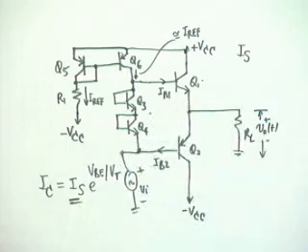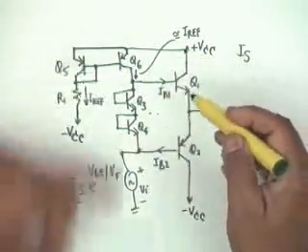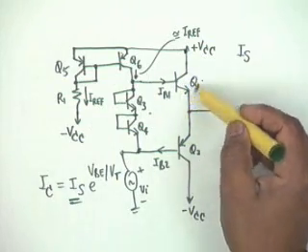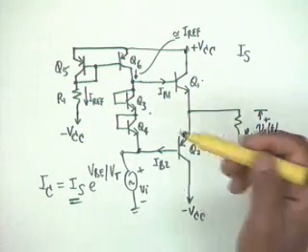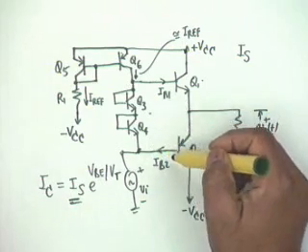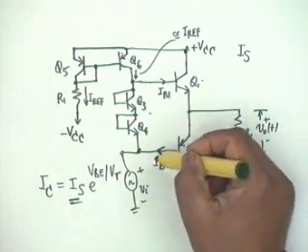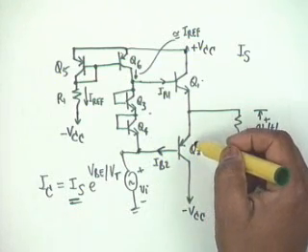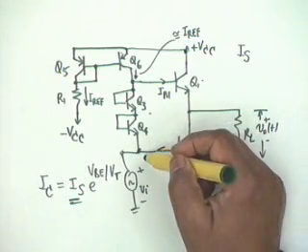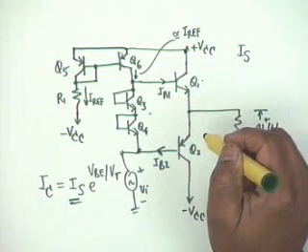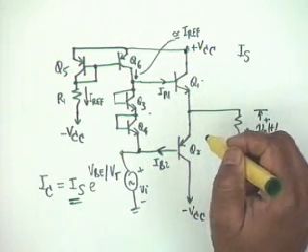So it flows like this, and in the path, while it flows, it gives out a small part IB1 because there is a bigger Q1 here. But it gets its price through IB2. Q2 gives some quantity back, and that's how it replenishes. But as I said, if beta 1 and beta 2 are large, then IB1 and IB2 can be ignored.